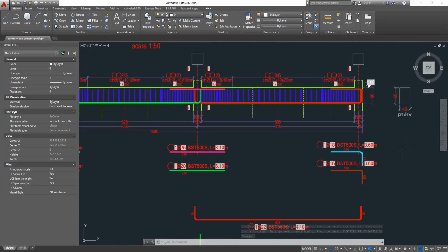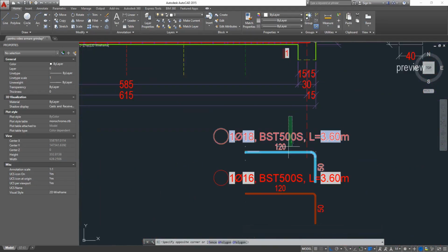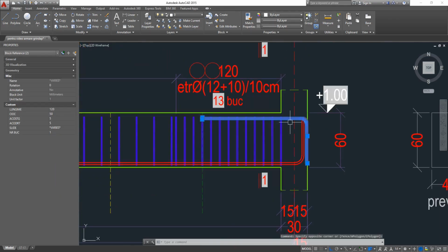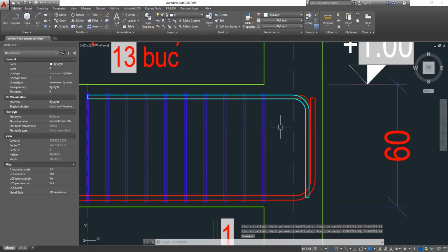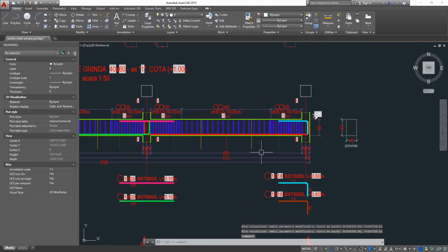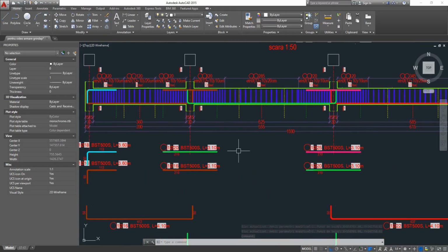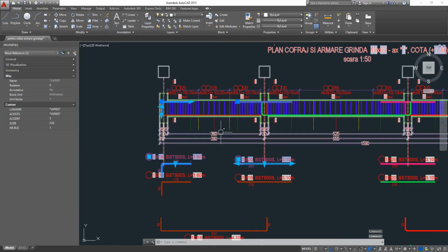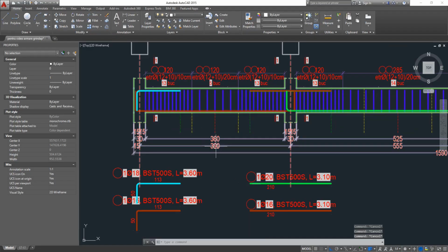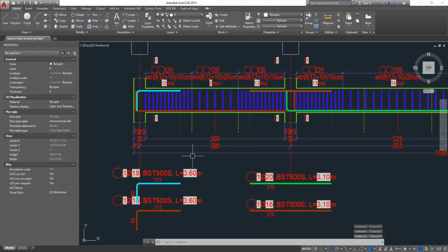And we're going to repeat that for the right rebars with the same command, but this time leaving 0 at the left and 7 to the right. Okay, now we're going to overlap the first set of rebars at the middle of each span of the beam.